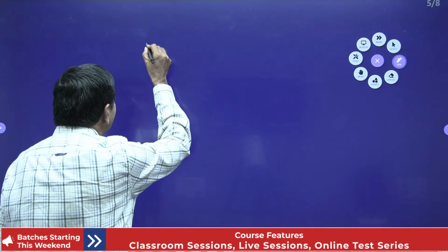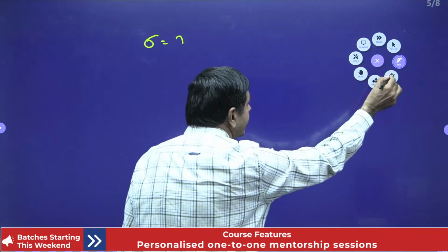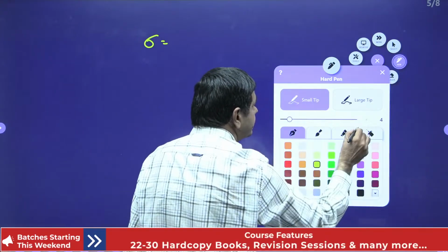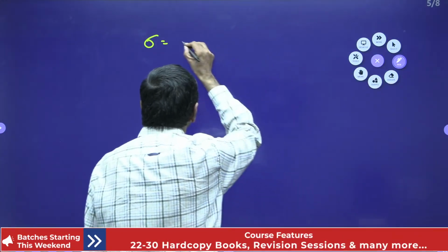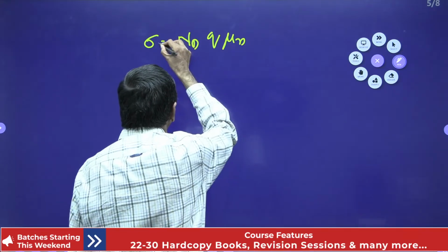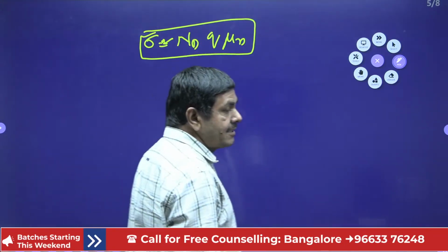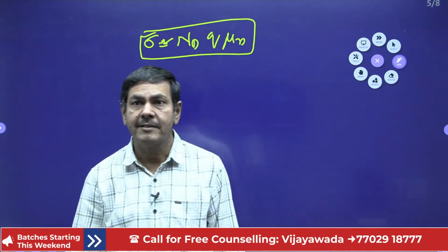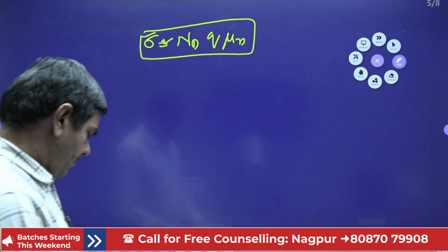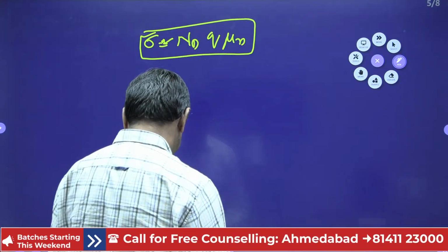But finally, what are we getting? Sigma equals, I'll write again, Nd into Q into mu n, approximately equal, as I gave already. Understand? That formula we are going to use. This information is very important regarding the n-type extrinsic semiconductor. But I would like to do one problem based upon this formula, so you can understand it clearly.